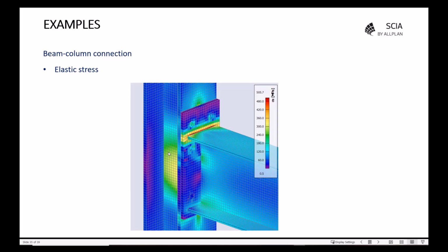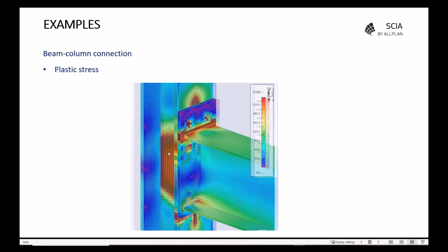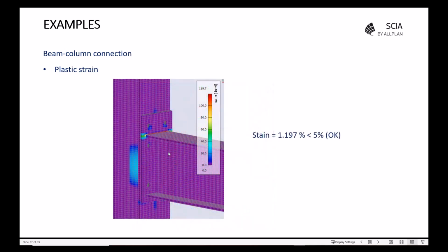So as results, for elastic stress, we've obtained 505.7 megapascal. For the plastic stress, we've obtained 235 megapascal. And for the plastic strain, it's 1.197%, which is lower than 5%, so it's okay.